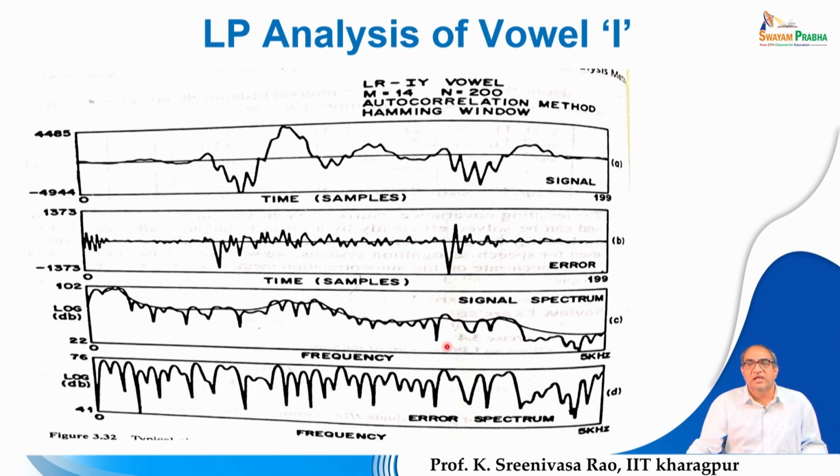For a periodic trend, the fundamental frequency, or the periodicity of the signal, is the more dominant frequency offered by that. So, you can see ripple throughout the spectrum, at the fundamental and its harmonics, right. Whereas if you look at the bottom, the fourth plot, this is the spectrum of the error signal.